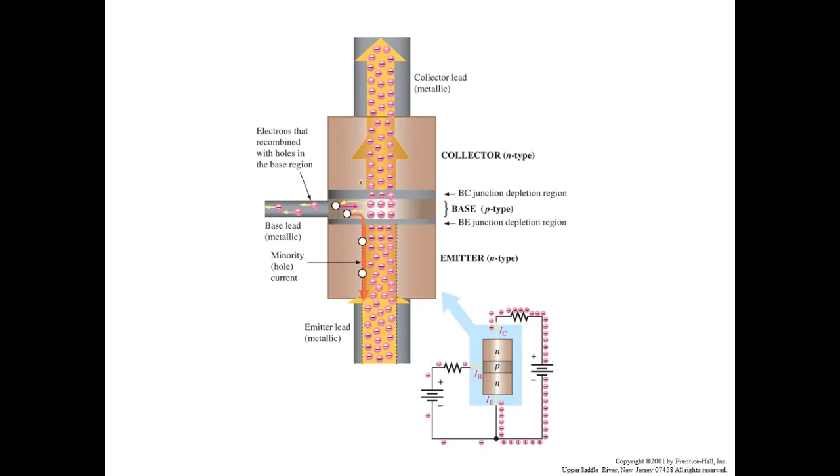And when these guys come flowing into that base, they don't have any holes to fall into, and they see that big old positive potential up in the collector, sucking those electrons up, right? You understand? So about 99% of the current goes up through the collector. And we've got a ratio we'll talk about, we'll call beta, which is in this chapter. It surprised me that nobody asked about beta, which is a really good question.